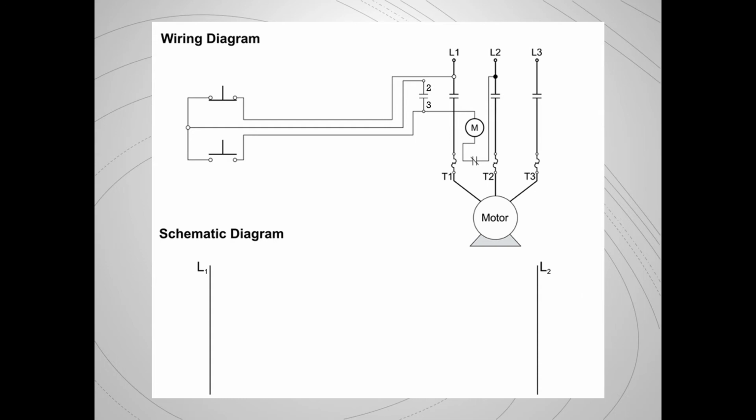I should also keep in mind that all the wires that are connected together from any one of those points should also share those numbers. I'm going to want to trace each and every wire through each and every contact and make sure that everything is labeled exactly the same all the way through.